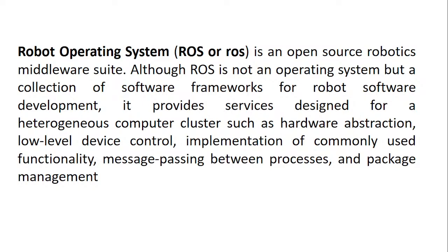By using wheel encoders, we can get the wheel odometry data, and by combining all these things, we can get an idea of the state of the robot. That is a very important factor in the Robot Operating System, because it can combine all these different data into a single state of the robot and its environment.